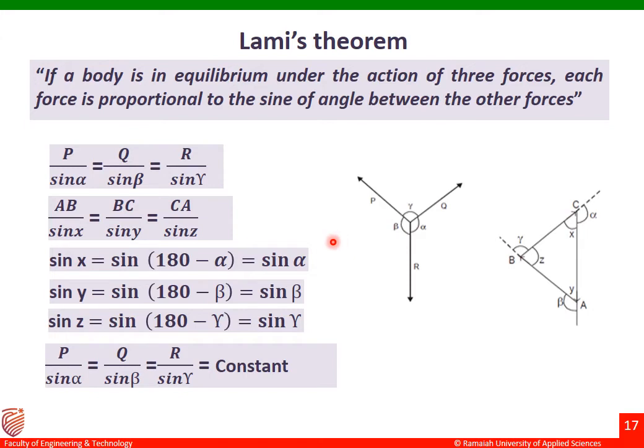This theorem states that if three forces acting at a point are in equilibrium, then each force is directly proportional to the sine of the angle between the other two forces. Let me repeat it once again. If a body is in equilibrium under the action of three forces, each force is proportional to the sine of the angle between the other two forces. This theorem, Lami's theorem, is applicable only when there are three forces. If there are two forces or four forces, this theorem is not applicable.